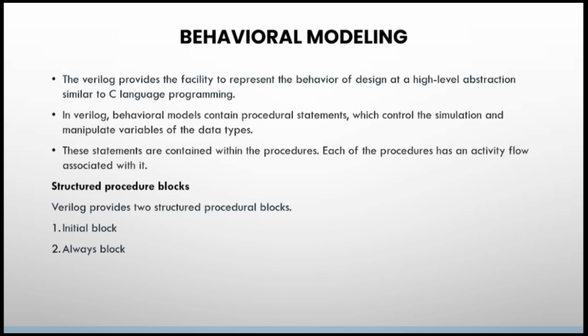Simply put, when we are analyzing combinational circuits, we go for data flow modeling, and when we are analyzing sequential circuits, we opt for behavioral level modeling. That doesn't mean that combinational circuits can only be written in data flow modeling and sequential circuits can only be written in behavioral modeling. But mostly, when we choose coding styles, we use data flow modeling for combinational circuits and behavioral level modeling for sequential circuits.